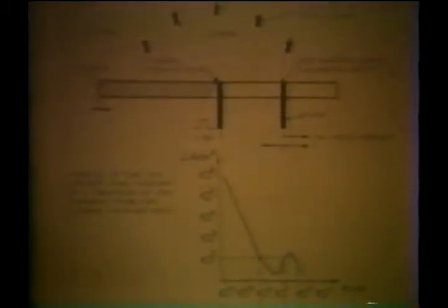In the energy balance of the cathode surface, the processes of electron emission and bombardment by the ions from the pre-cathodic zone were taken into account. The calculation has shown that the energy release in the cathode spot is dominated by a Joule volume heat source. The contribution of ion bombardment to the energy balance is very small.